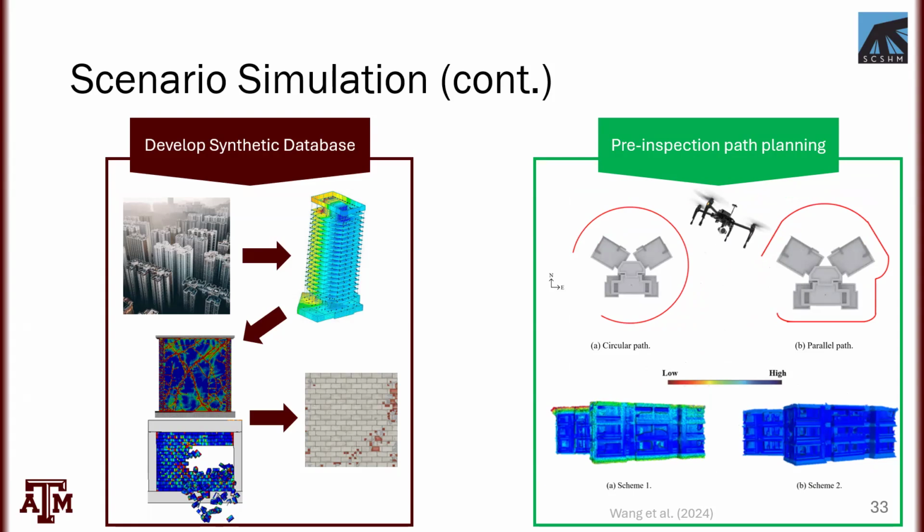You can use the digital twin environment to optimize the path planning before your actual deployment. It saves you time, it saves you battery life when you're out there, and improves the quality of your data set. So you can find out what is the best path that gives you the best coverage quality when it comes to your points, your point clouds. And also within the digital twin environment, don't forget, you can change and check a lot of different environmental conditions, lighting, cloudy days, all those things.